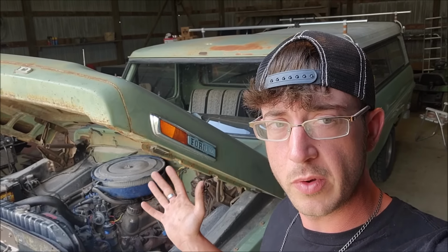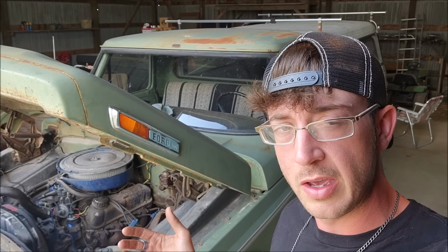So in the case of this vehicle, the first thing I need to do is get the air filter housing and carburetor off of the engine. There's a few different ways you can skin this cat, but we put a spacer adapter in the kit where if you do have a 4-barrel intake, this is exceptionally easy where you don't have to think at all, and that just happens to be what this truck is. So let me get all that off, and then we'll look at all what comes in the kit.